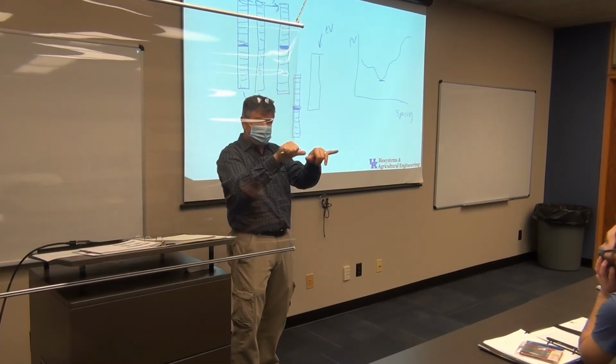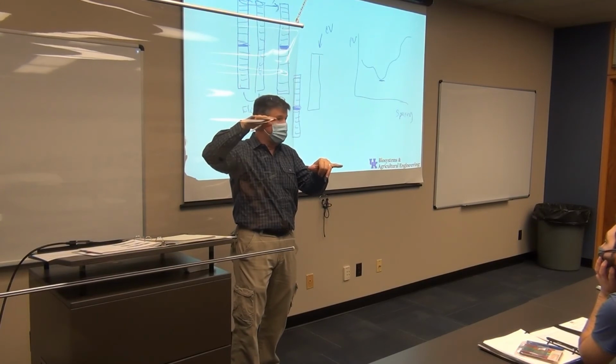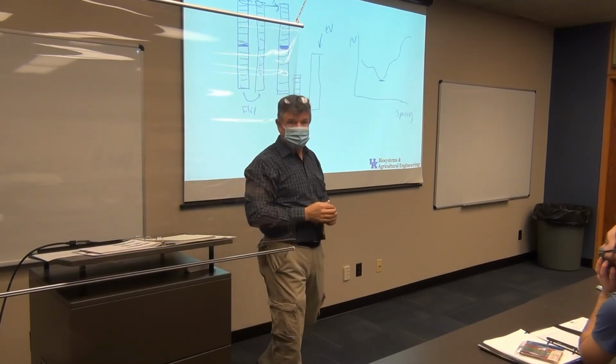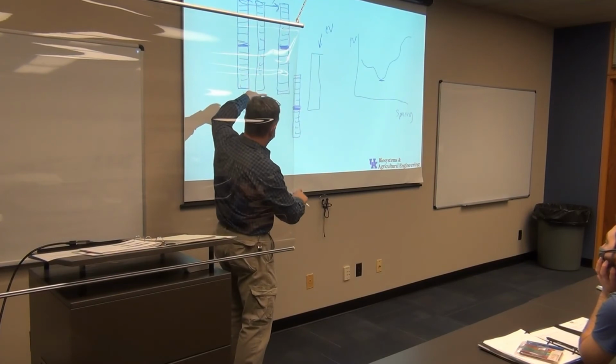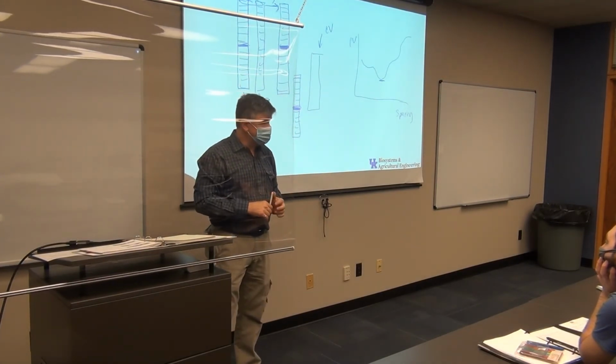This is how much it should overlap to give me the most uniformity that I can achieve. This is as uniform as I can get. That's ultimately what I want to get at. And then that becomes my recommendation. Then I say, that's how far apart those nozzles should be.